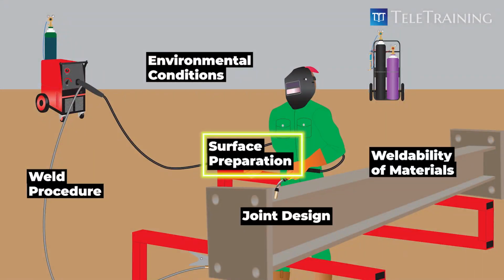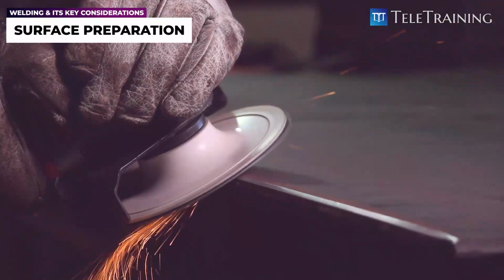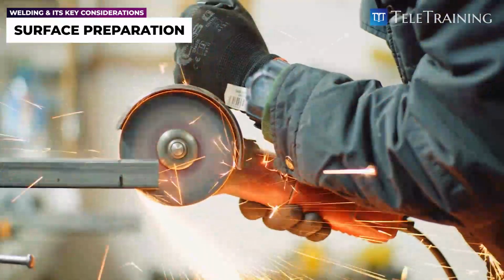Now let's look at the surface preparation. Surface preparation, like cleaning the joint, is another important factor to consider before welding, to remove all the grease and dirt, which could contaminate the weld, or tapering or chamfering the edge of the steel, for butt welding.